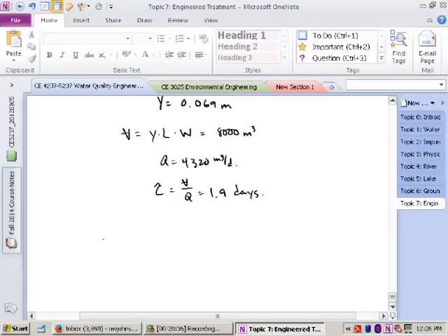So what this looks like then is, if you think about it, it's 800 meters times 0.0005. That's 0.4 meters, right? So over this 800 meters, it's dropped by only a foot or so. So it's pretty flat. Put a weir in, huh?